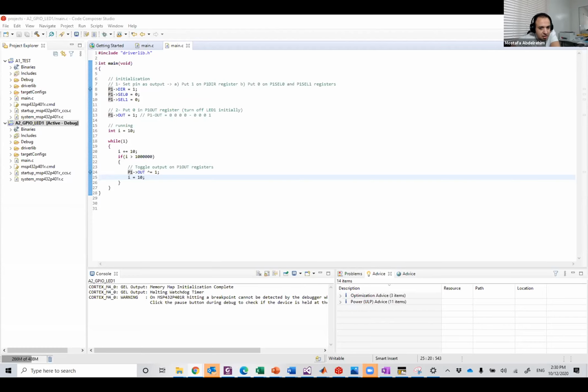Properties. Then include options. It's in the middle of the left hand. Yes, include options. Add. You see this green plus? Yeah, add workspace. Lab2. No, no. Workspace again. Yes, driver lib, again driver lib. Hit this guy. And apply and close.